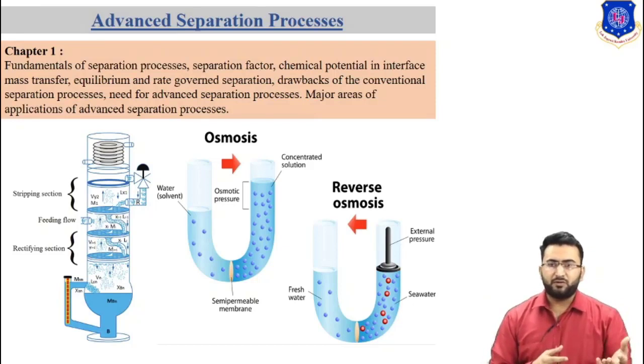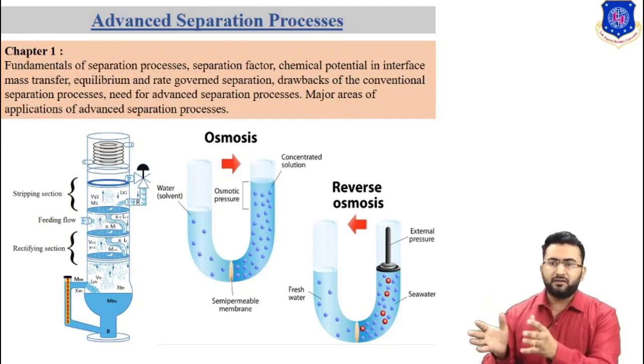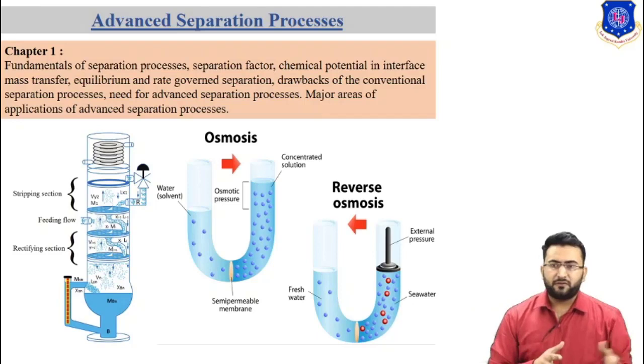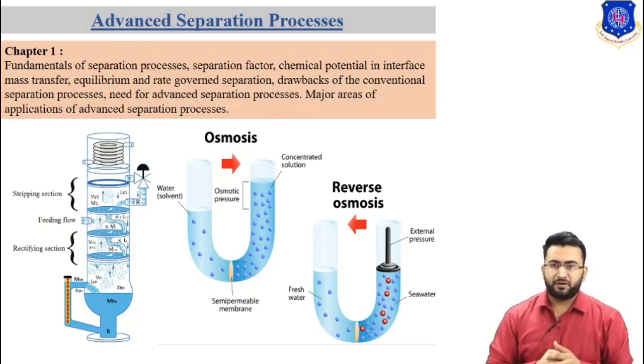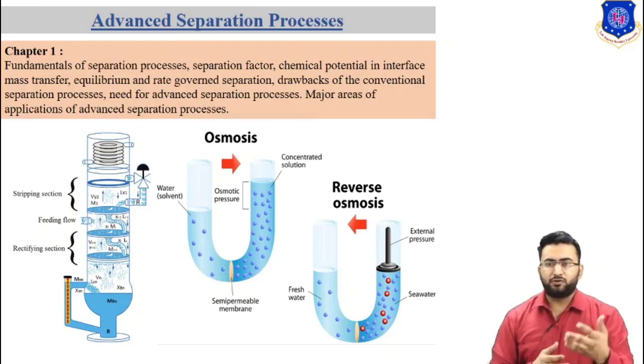Now if I add this component C to the mixture, component C forms a mixture with either A or B. In other words, either component A or component B is miscible in component C. Let's suppose component A is miscible with that solvent, then it makes a mixture of components A and C, and B will be separated. Now further we have to separate components A and C. For that we have to use distillation.